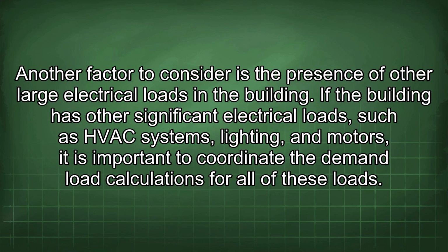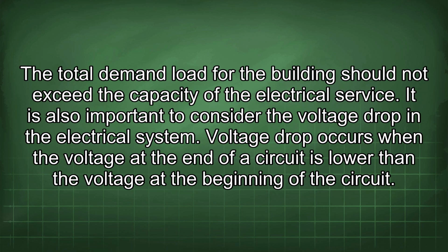Another factor to consider is the presence of other large electrical loads in the building. If the building has other significant electrical loads, such as HVAC systems, lighting, and motors, it is important to coordinate the demand load calculations for all of these loads. The total demand load for the building should not exceed the capacity of the electrical service.